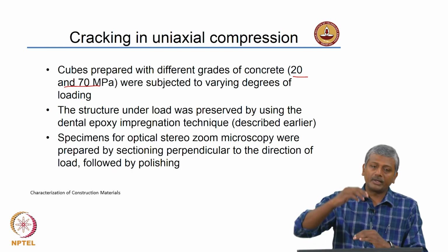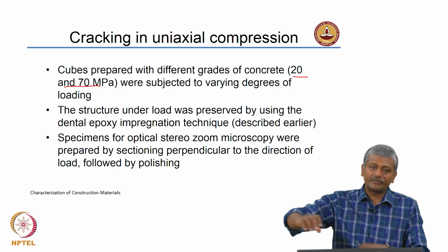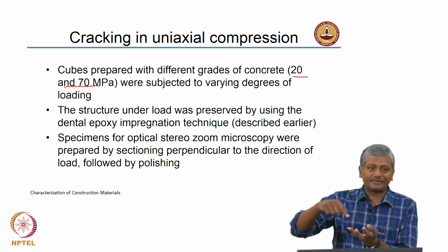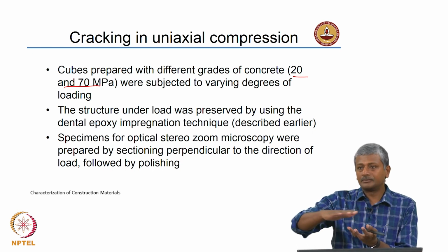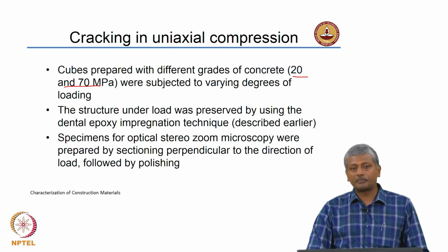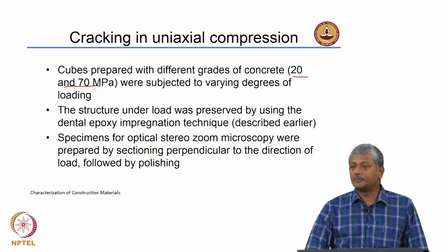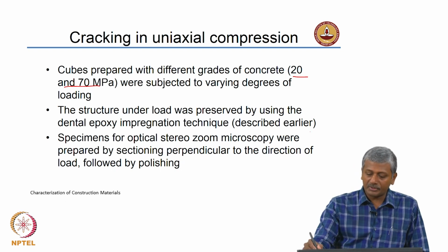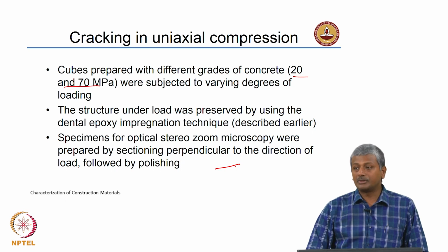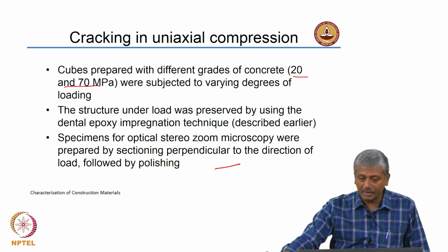And then after unloading, these were sliced and polished, and the projection of the cracks in the horizontal plane was imaged using an optical stereo zoom microscope, which had limited magnification, up to 70 to 100x, not more than that. Again, structure was preserved by epoxy impregnation, which we described earlier. Optical stereo zoom microscopy was done on the polished images.